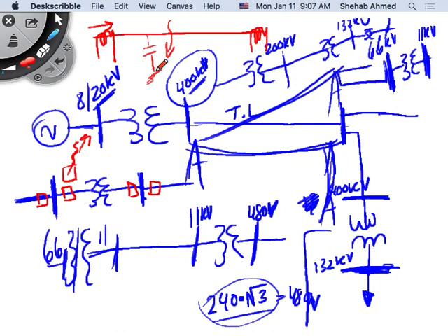Again, if you have any potential difference between devices, then you have a capacitor. So if you have something at 1 kilovolt, and you have a piece of metal at ground potential, then even though you don't have a physical capacitor there, this is equivalent to a capacitor.